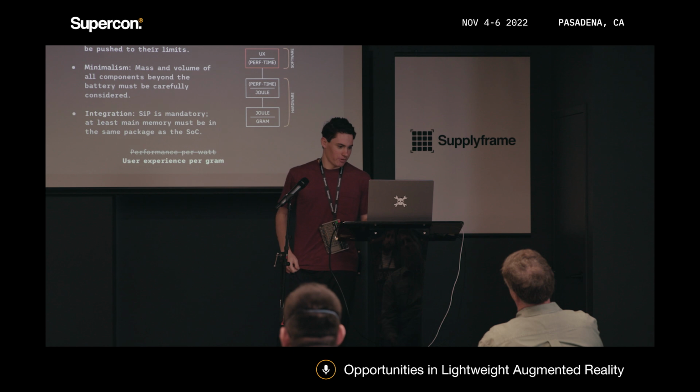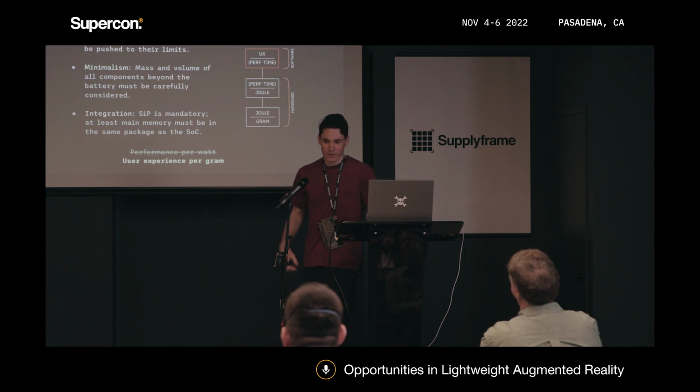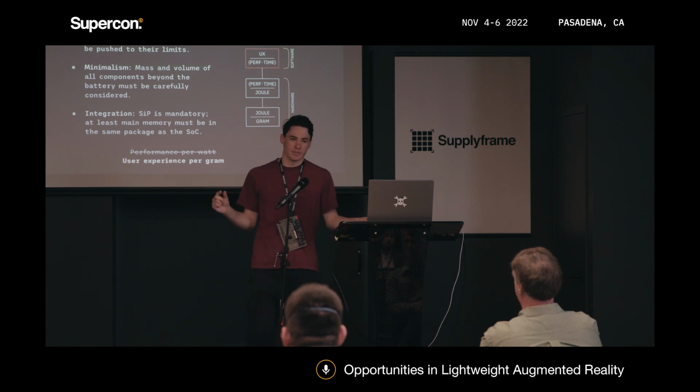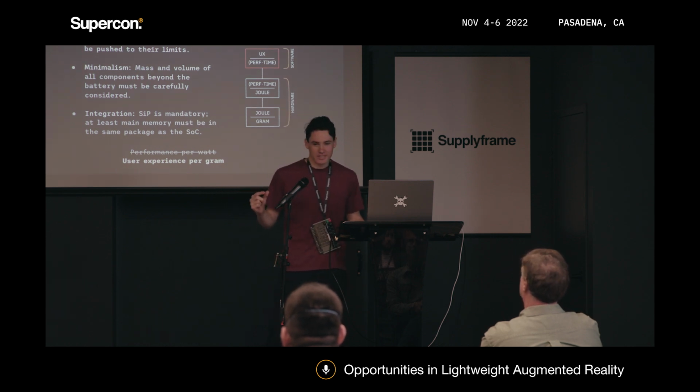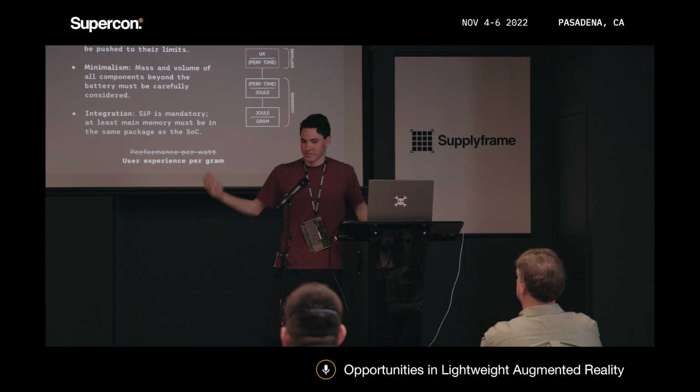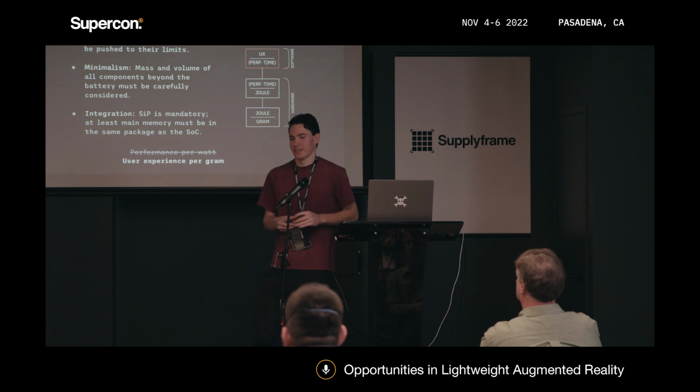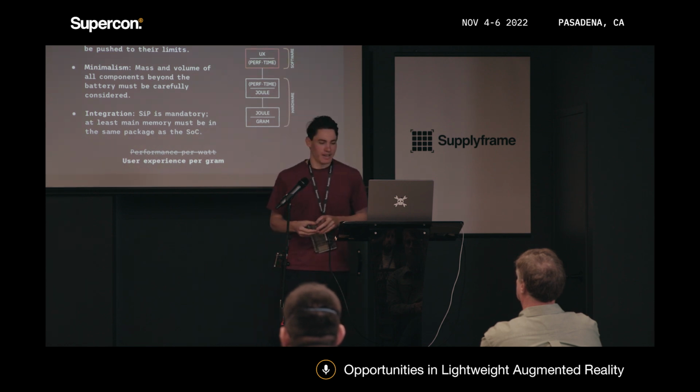From that point, I moved into how do we improve this? Now, one thing about that STM32MP1 microprocessor is it's not terribly power efficient. If you run the display and just have Linux sitting at idle on that system, you're typically looking at over 1 watt, just with Linux idle, display on and everything like that.